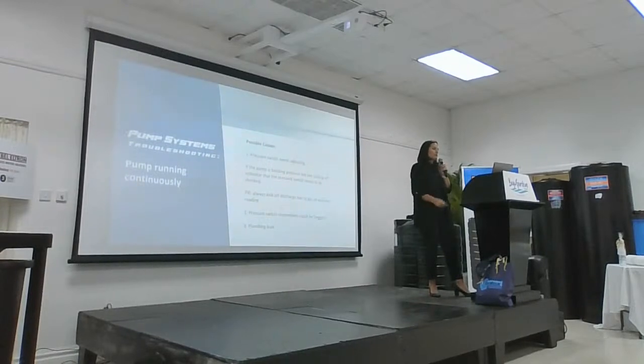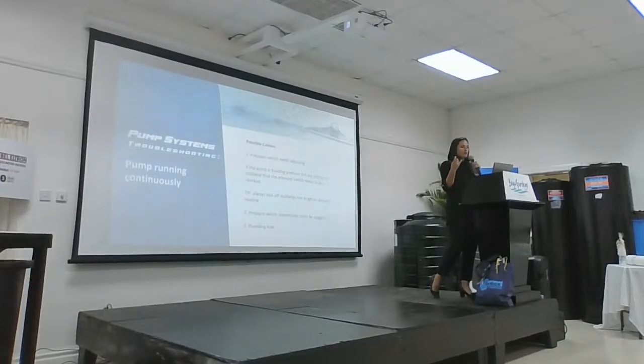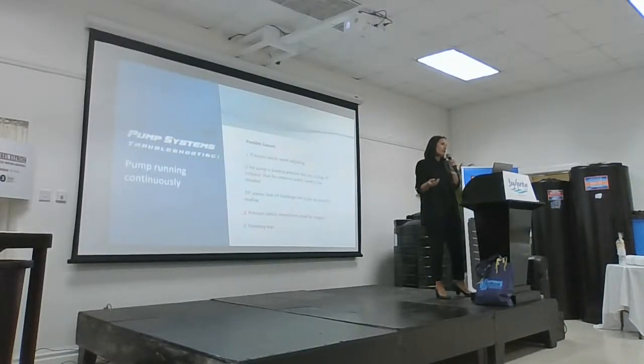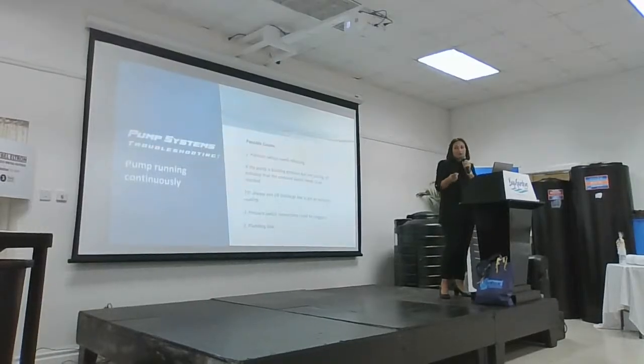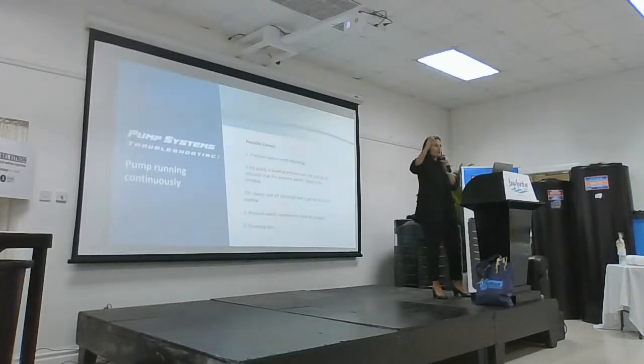Another possible reason why your pump may be running continuously is a pressure switch. Your pressure switch connection can be clogged. Or if it's a smart head system or pressure system, you may have a leak on your line. The smart head system is actually great at detecting this because your pump will run continuously non-stop. Whereas in a pressure tank system, you may cut on and off, but you have periods of inactivity when your pressure tank is full and draining down.